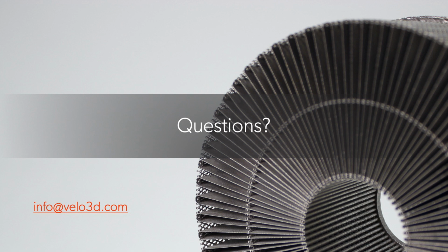Yeah, so in regard to the explore mode, keep in mind that that one is really geared for a design exploration standpoint. So the short answer to that one is that we are not considering the surface roughness. The reason is it requires higher level discretization, a little bit more complexity from the physics perspective. So what we've done here in Discovery is allow it just to be basically a standard no slip wall condition where you're not considering the surface roughness. But what you can do directly from Discovery is transfer this directly to our Fluent product. All your boundary conditions, your mesh, your materials, your geometry, you can bottle that up, send it directly to Fluent, where you can simply just turn on your surface roughness.